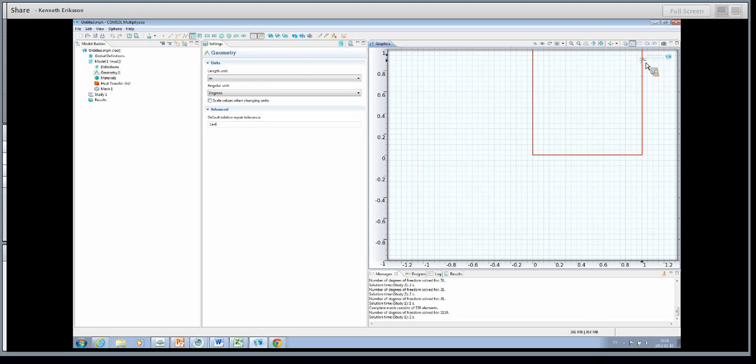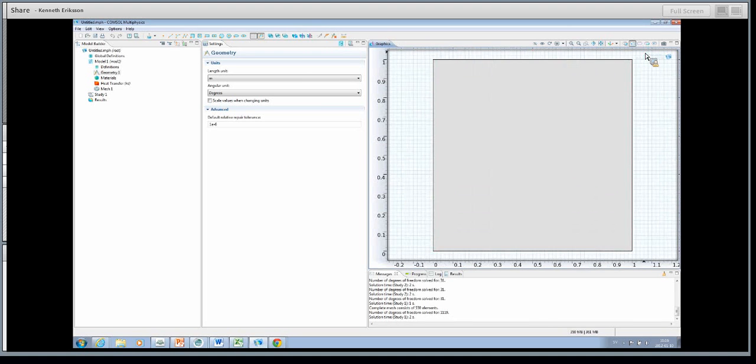Next, I would like to subtract or define a circle to subtract here. And this circle should have its center up here and have a radius, let's say 1/2. So I pick this type of circle where I specify first the center point and then mouse drag to specify the radius. So I start here, left click, and I draw a circle which has radius 0.5, like that.